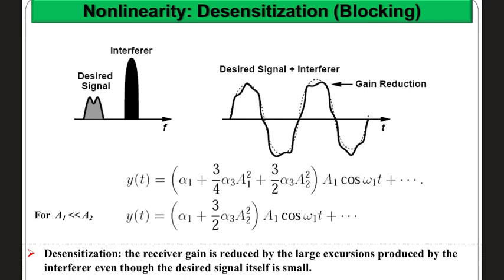Yeah. FM is a different story. If A1 was dominant, I'll get A1 cubed, not only A1. That's fine, because you will have A1 because of this constant term, and you will have A1 cubed. That's fine, it's still your signal. A1 is sufficient for you, right? And if you are very keen, you can also do some processing of that polynomial to recover your actual signal, because it's all your signal, right?